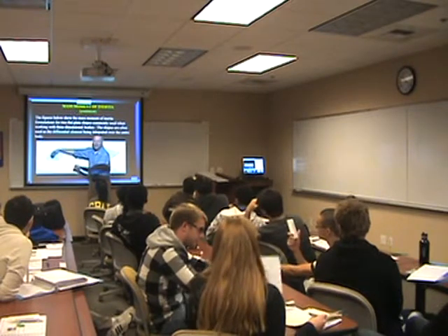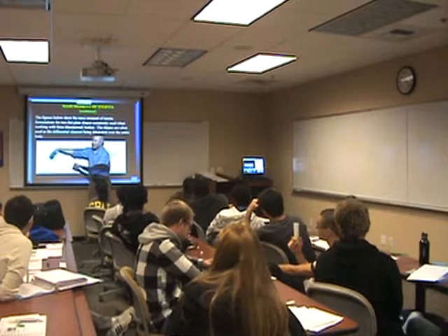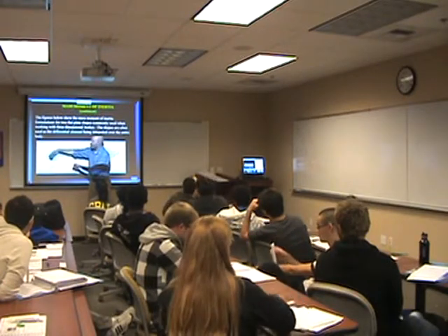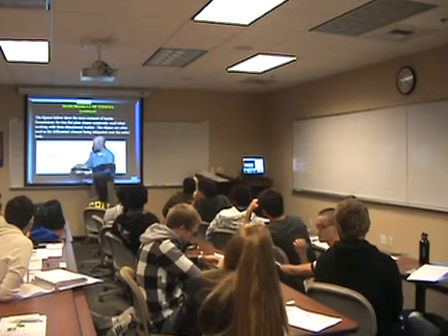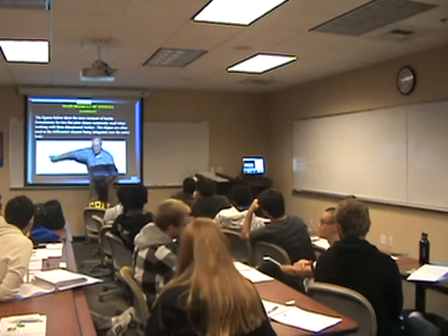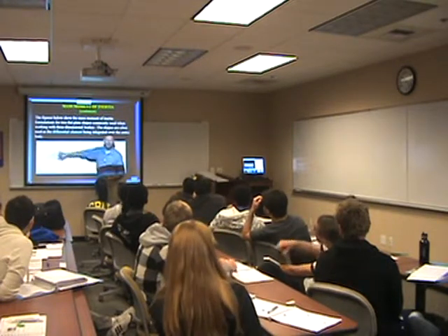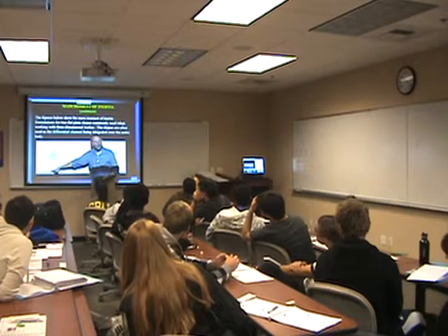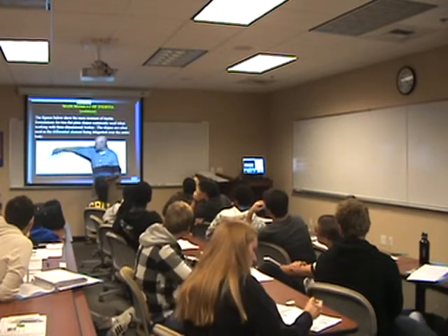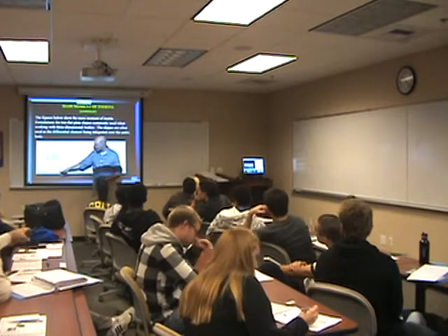What is Ixx? Now we're rotating our yo-yo like this. That would be Ixx. So Izz spins this way, Ixx spins this way. And so if we're rotating about the x-axis, we're flipping a coin. Rotating about the y-axis, we're also flipping a coin. And it's equally as easy to flip a coin in either direction because of symmetry. But to spin a coin, it's harder to spin a coin. So that's 1/2 mr squared.